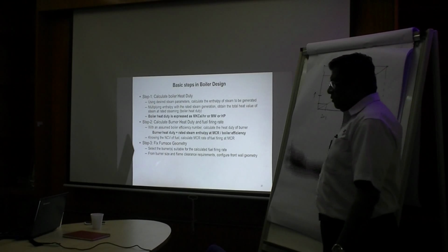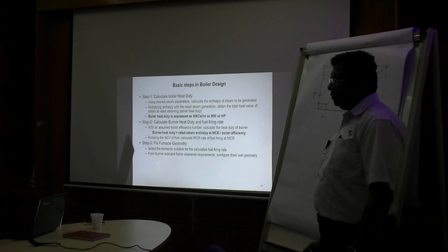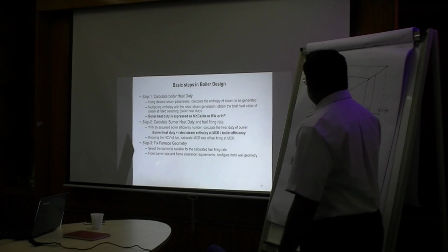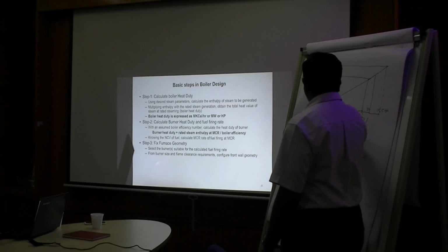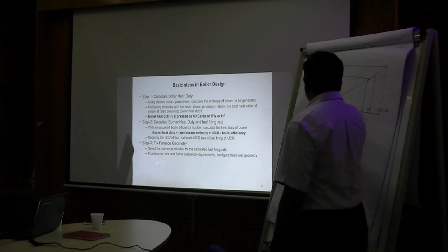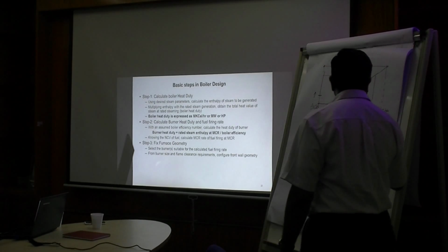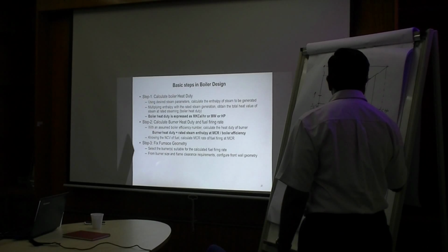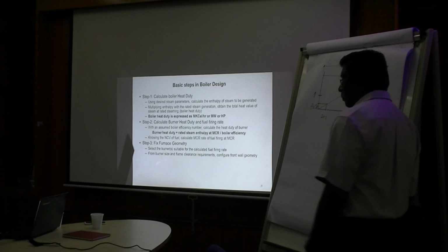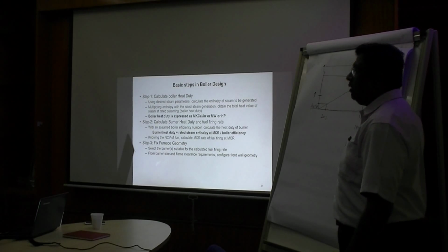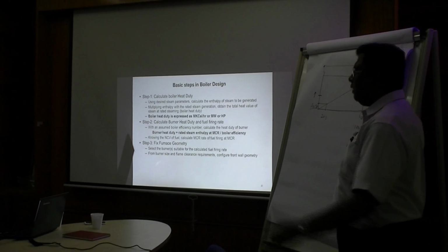So will one burner be sufficient in that case? Because you needed 20 ton steam on a stable basis. You selected a burner for, let's say this was 100 tons per hour. So the burner was basically designed for a heat duty equivalent of 115.5 TPH. What is the turn down? 1/4 of this will be roughly 30. Say 29.